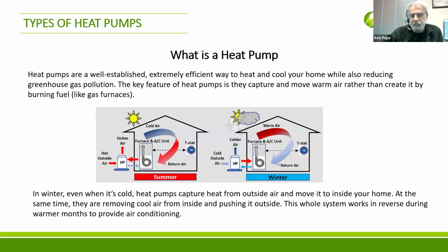It captures it from one place and distributes it to another place. So in the winter, it's capturing the heat from the air that's outside, and believe it or not, no matter how cold it is, there's still heat from a heat pump point of view in the cold air outside. It concentrates it from outside and delivers it inside. So that's how it works in the winter. In the summer, it's doing the opposite. It's taking that heat from inside and dumping it outside.